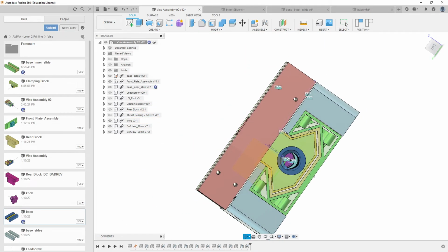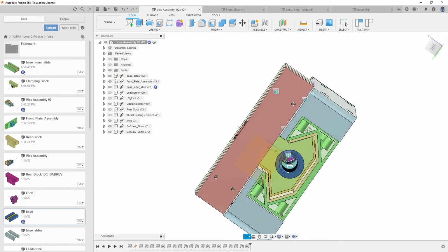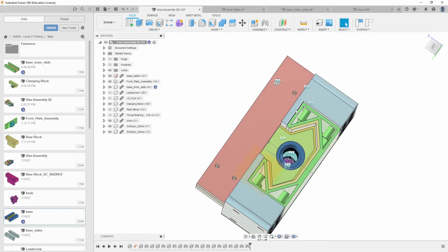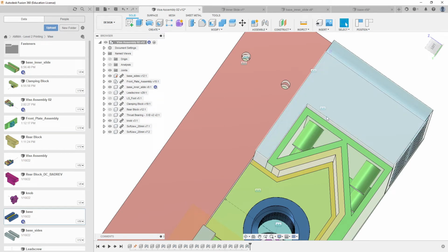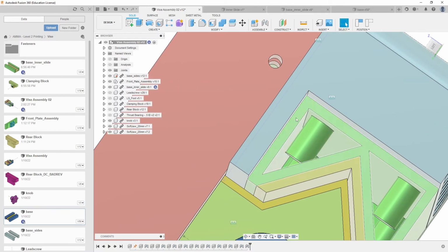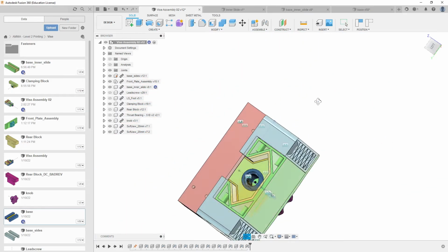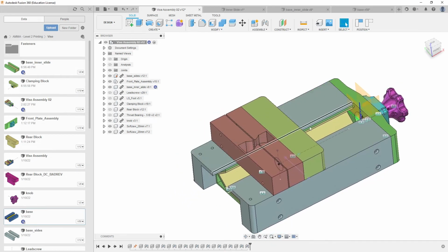But you don't want to mess with your hole alignments, but that could be the reason you need to do this, because maybe you try to adhere these, bond these two together, fasten them together, and maybe your holes seem like they're not lining up by a really small amount. Again, it might be your fitment right here that maybe you need to shave this down by just a tiny little bit. The holes will belong where they go. If you were to shave a little bit, again, you would just have maybe a small little gap right there, right? And that's all, that's it.